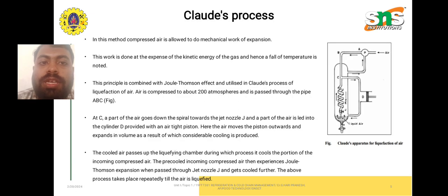Claude's process. In this method, the compressed air is allowed to do mechanical work of expansion. This work is done at the expense of the kinetic energy of the gas, and hence a fall of temperature is noted. The principle is combined with the Joule-Thomson effect and utilized in Claude's process of liquefaction of air.